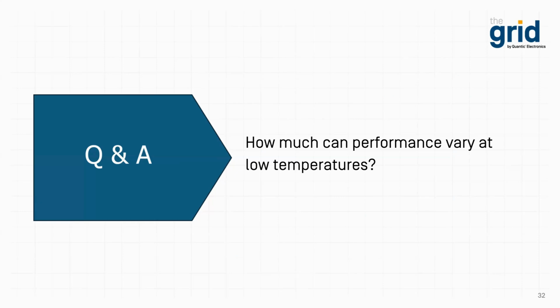Oftentimes, there's other areas of design to look at, but oftentimes, that's your baseline. Worst case scenario, and that's where you start. And how much capacitance do you need at that worst case scenario? But again, the short answer is it depends on the technology, but up to half of the capacitance can be lost at extremely low temperatures.